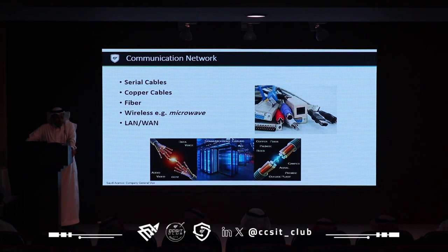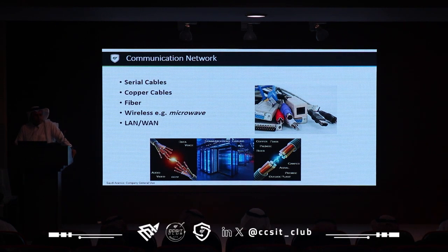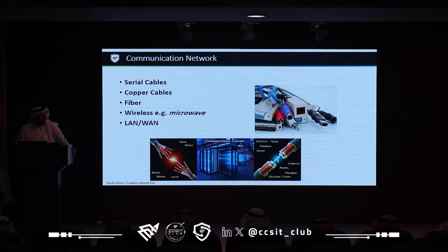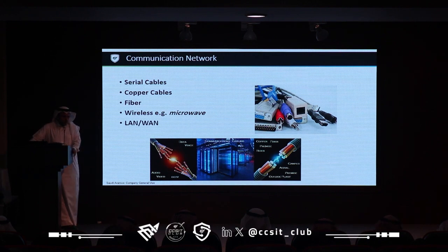Definitely, the main risk of attack is in the communication media. You can tap into the communication, sniff the data, and insert your own packets. But most of the communication is controlled, and we are now transferring to more secure protocols. For example, DNP3 has an authentication process.